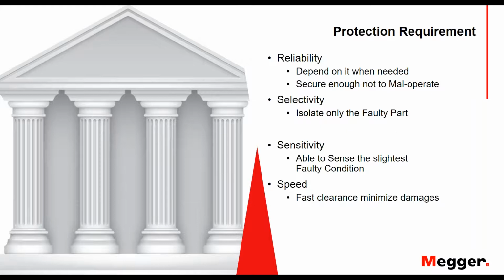After that, you have selectivity, and basically it means isolating only the faulty part to minimize the downtime or the affected area as much as possible. This selectivity is in most cases what we desire to have, but sometimes we are not able to achieve it due to constraints in cost or in performance.